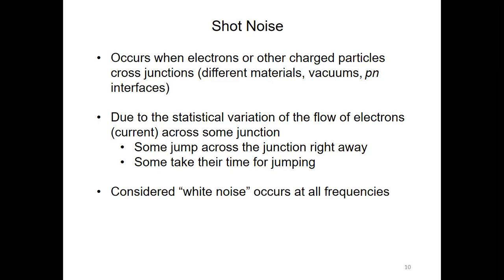Because of that, the flow rate of the electrons will change. Therefore, the current will change. When these changes happen, they will be detected by the detector and the readout device as shot noise. And this one is also considered white noise, same as the thermal noise, because it does not depend on frequency. It occurs at all frequencies, right? That is shot noise.